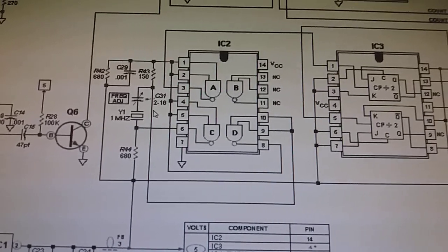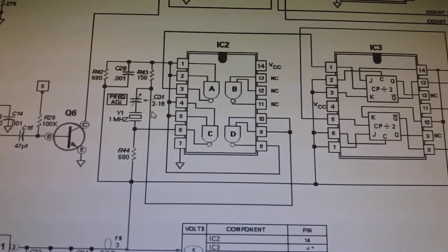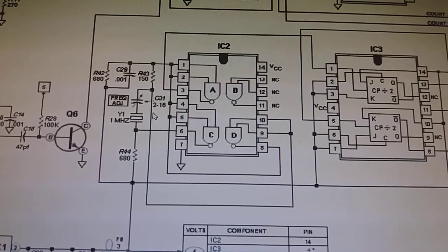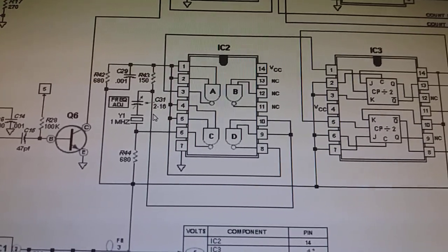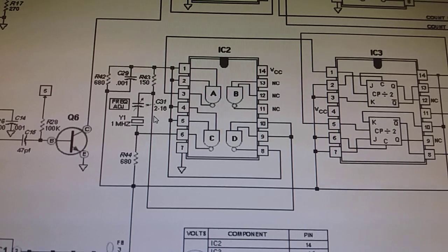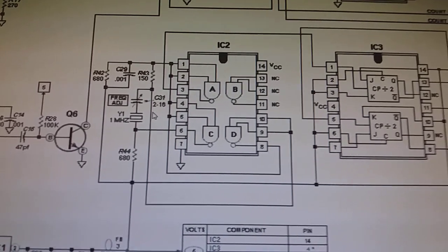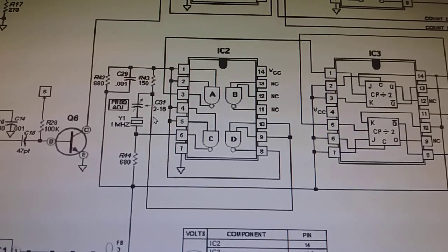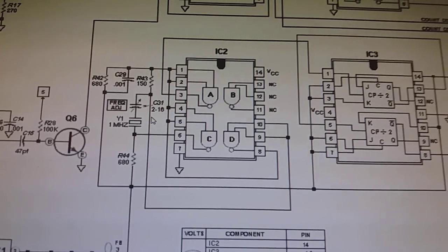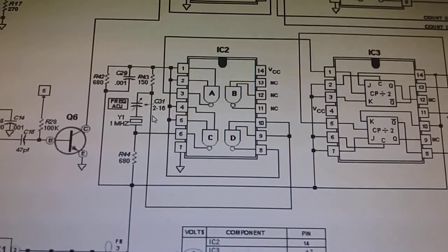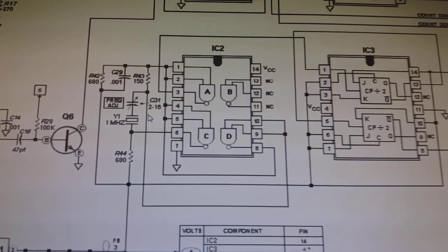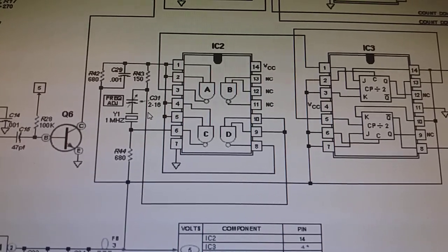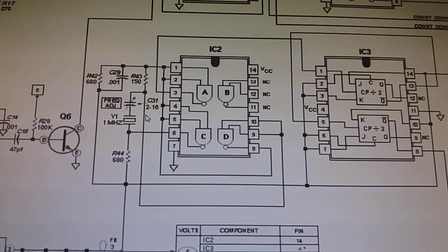And the other thing I could do is put a series capacitor with this variable capacitor. So instead of 2 to 16 picofarads, for example, I may put a 2 picofarad or even a 1 picofarad capacitor, and then I'm gonna have a very small capacitor there, yet adjustable, but with a very low adjusting range. But we don't need a very high adjusting range. Even 2 picofarads is too much at this point, so we don't need much more capacitance than 2 picofarads.